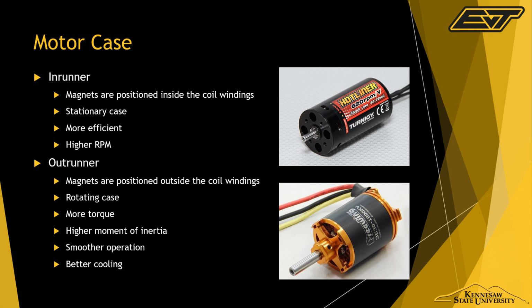I mean, I guess they don't have to, but you really should. But with outrunner motors, the case actually cools it, which is really cool. If you know how a fan works, or a radial fan, I think is what they're called, the motion of the case spinning will cause air to be flung out of the motor, which is the best way that I can describe it. So that's why outrunner motors are so much better than inrunner motors.